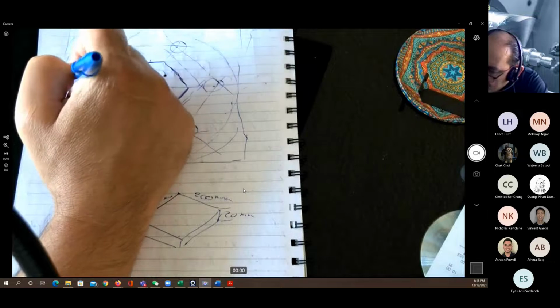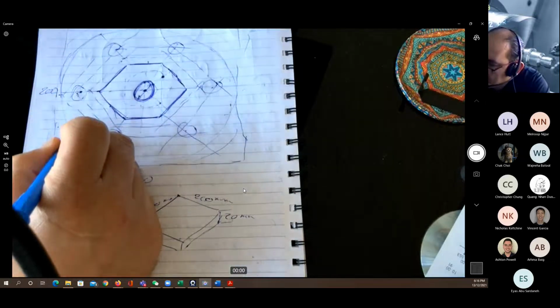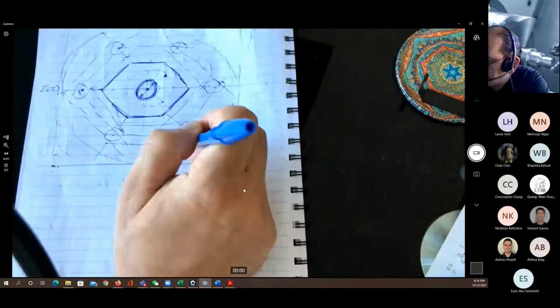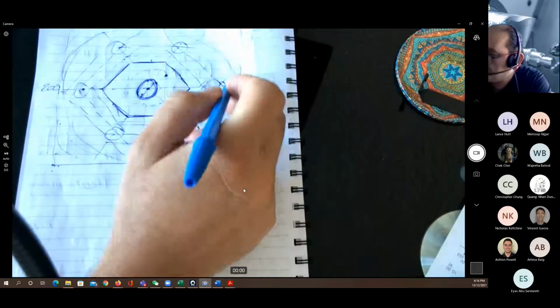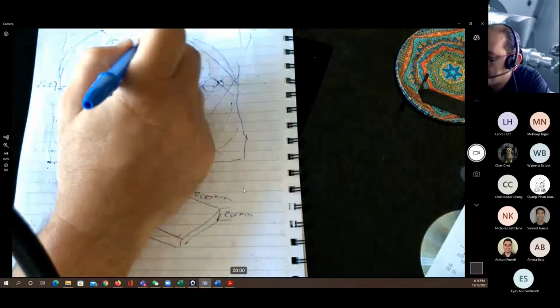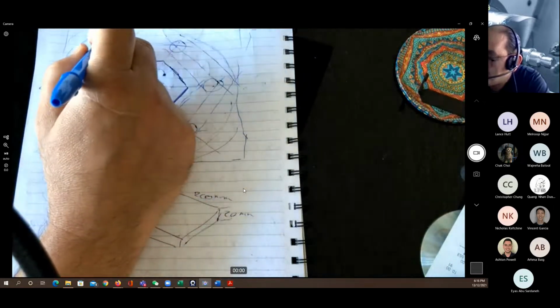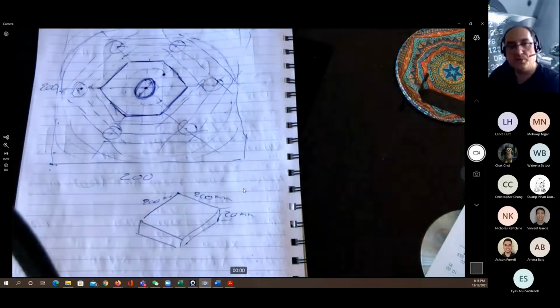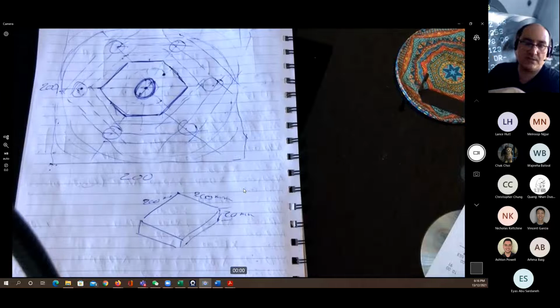Okay, another extension by 6 millimeter. Now you can see that I always choose 6 millimeter as the offset. This is for two things. First, I try to do some standardization for my cut, so I'm always going to have the depth of the cut be 6 millimeters. Also, I don't want to put extra forces on the cutting tool when it's going to do the cut.